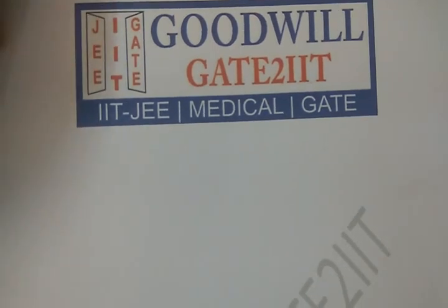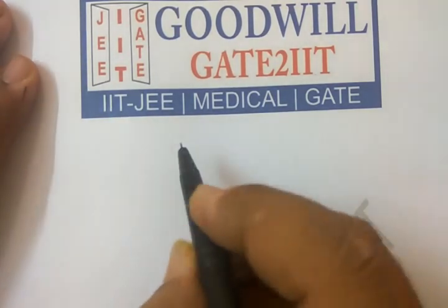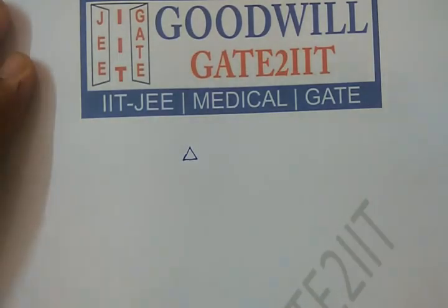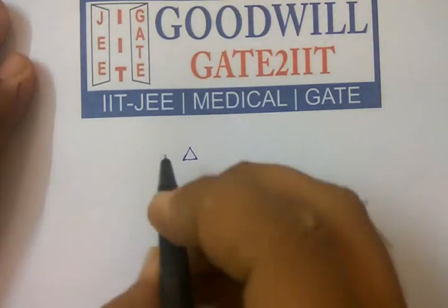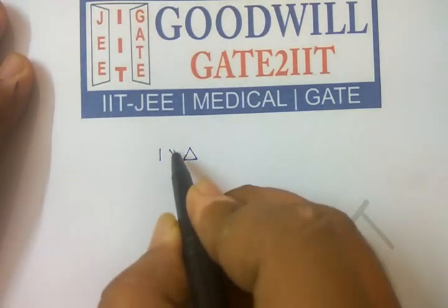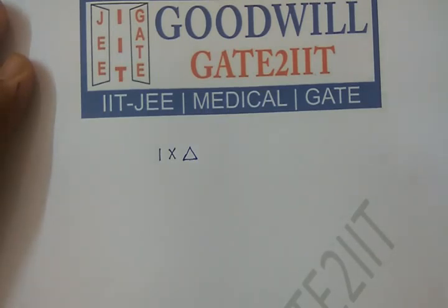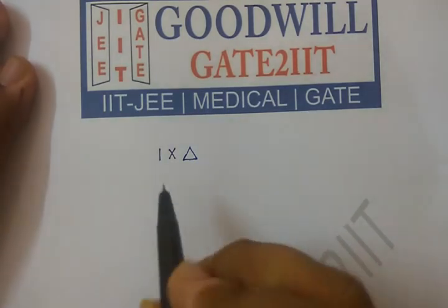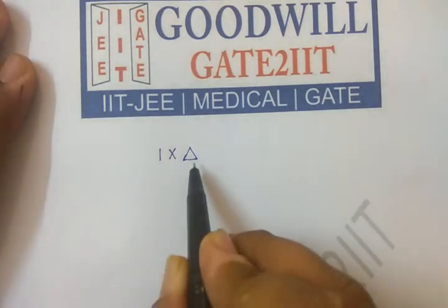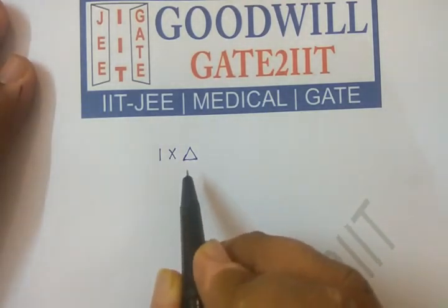So just keep a few points in mind. What we are interested in is calculating the deflection at any arbitrary point. Let's denote this by delta. So what I'm going to do in the virtual work method is apply a unit load. Now this is a virtual load, it is not actually present. So we'll see how to solve the numericals. So 1, which is the load, into deflection. Load into deflection is nothing but the work. So for this reason we are naming this the virtual work method.